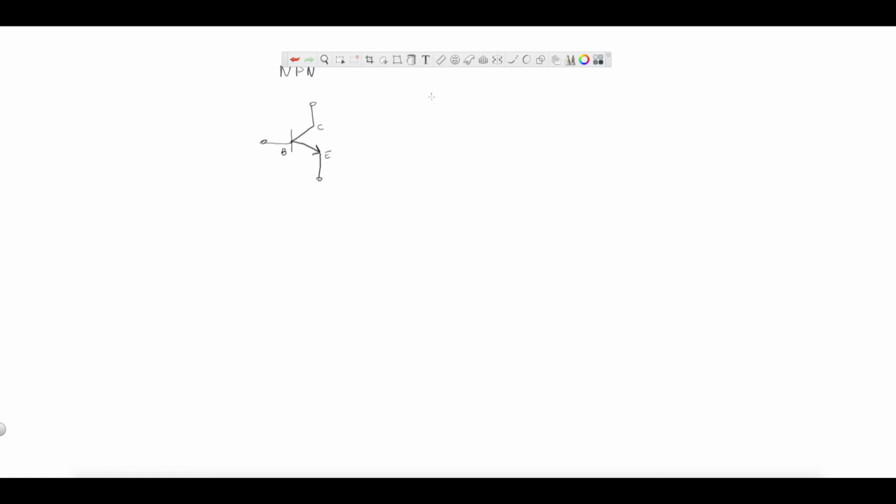So how is this structured, mechanically speaking? If we have all the semiconductor junctions to represent this transistor, it would be something like this. The base is connected to P, so this would be the base, this would be the collector, and here will be the emitter. So what we have is a junction right here that we need to break. It's a forward junction where, for this transistor to work, we need at least 0.6 to 0.7 volt in DC for this transistor to operate.